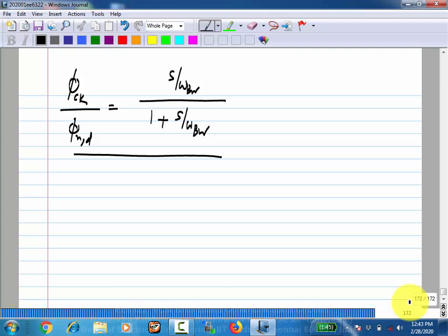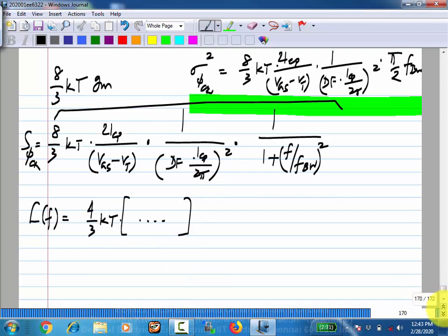Now we can make some quantitative calculations. Okay. Earlier, we just came up with the topology. We didn't know how much ICP to use, how much C to use, and so on, right? So now we know a few things like the value of ICP and C essentially affect the bandwidth of the clock and data recovery. That is how fast of an input jitter you can track and so on, and the noise, etc. And for a given bandwidth also you can see the expression for the bandwidth.